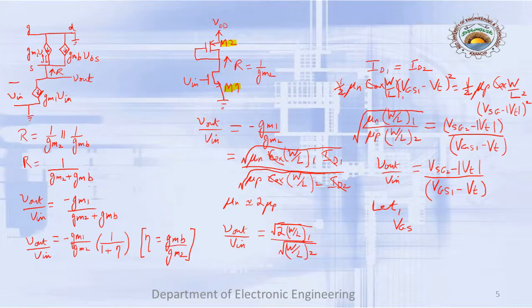So you see, now the width to length ratio, the W by L1 and W by L2, we see that if we want a gain of, let's say, 100, then the W by L ratio would be only 50. Or earlier it was 100. So the disparity between the sizes of the two transistors, because just imagine if we have two transistors in a configuration and one transistor is about 100 times the size of the other, it would be very difficult to place them properly. So that becomes the layout. The placement of the transistor is actually called the layout issue.